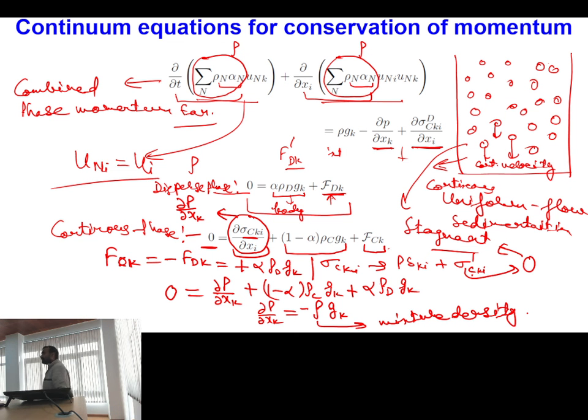Is this point clear? All are clear with this idea? So it means that whenever particles are falling at constant velocity, the weight of the particles is balanced by the hydrostatic force acting because of the fluid. Only then are they moving at constant velocity, because if these forces are not the same, there will be acceleration of the particles.